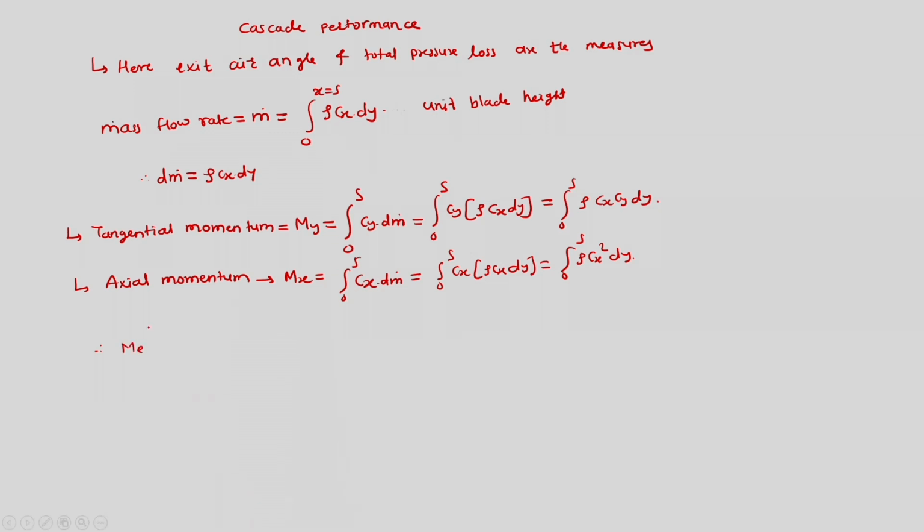So this integration we are doing in the blade passage. We are not saying that there is only one velocity which is existing and it is uniform. We can draw the velocity triangle at different locations, since velocity is varying in different locations in the passage, and this is integrated over the passage to get the complete variation accommodated.